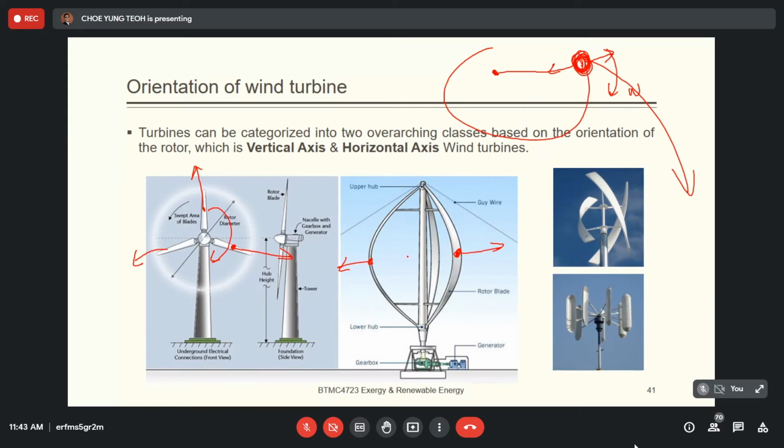you can see that at different locations of the blade, it will have a different angle of attack. So you need to move to a certain location before the wind is able to create the lift force. It's a good advantage that you can accept wind from all directions, but the bad part is at the starting point. You need to make sure that the wind hits from the correct direction.